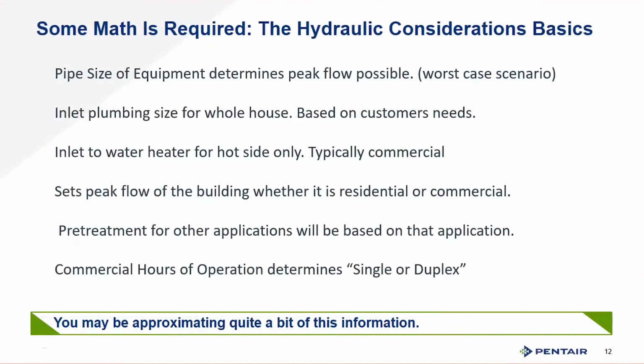Do they need whole house softening, or do they just need hot side? Hot side is going to be the inlet to the water heater. This is typically done in commercial applications because hot side is where all the real big financial gains are made from softening. Whereas in a residential application, it's about the overall experience and preventing scale buildup. There are commercial cases for doing whole house softening as well. It just tends to have the best economic impact on the hot side of things.